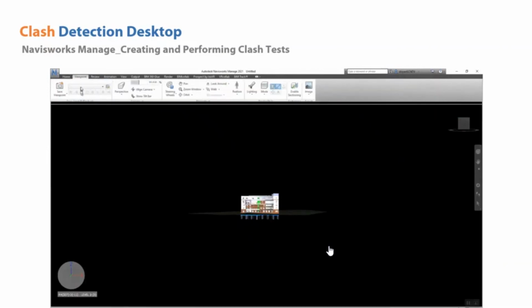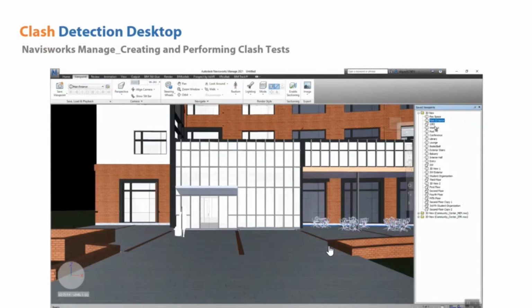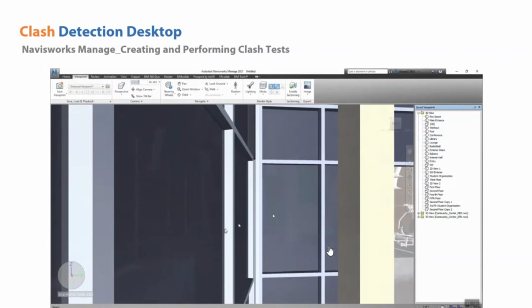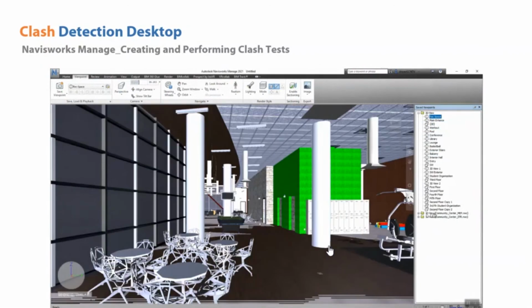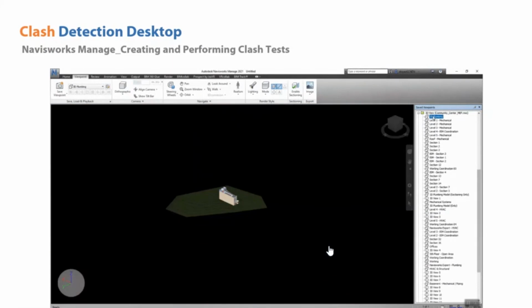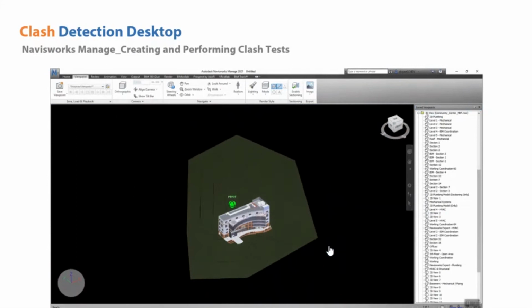So basically, Navisworks can append all project disciplines in one single environment to create a federated master model. And these master models can be used for many different purposes, including the clash detective process, so that all the views created inside the model authoring software will be preserved inside the model itself, so that we can go and review, or even create markups, or we can check the measurements on the model itself.